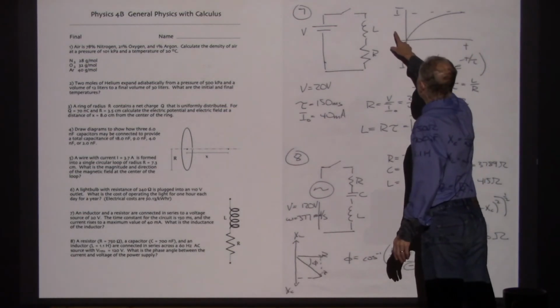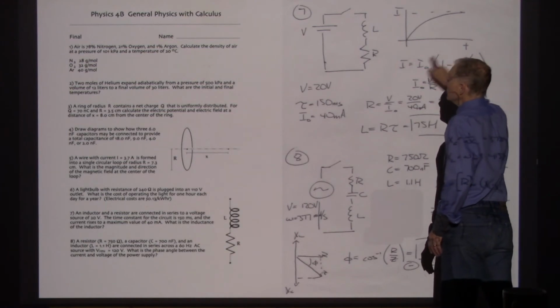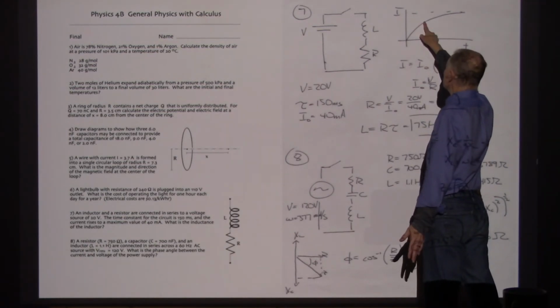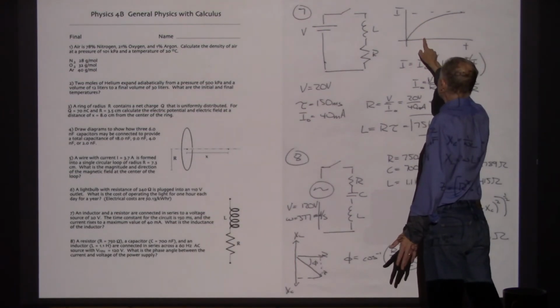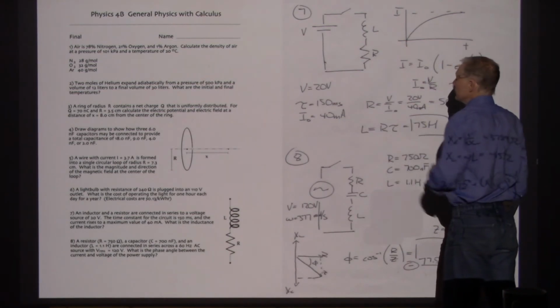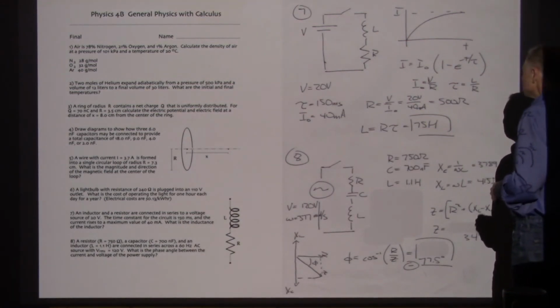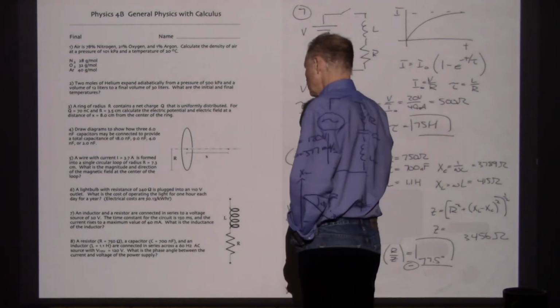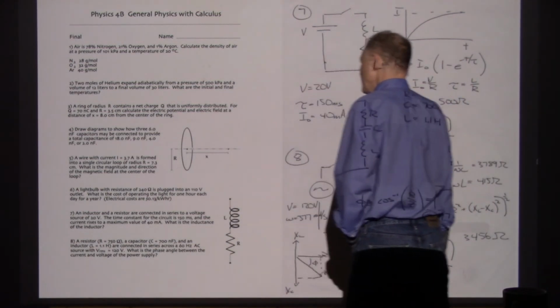So we've gotten out an oscilloscope and we've actually plotted the current as a function of time. Or similarly, we could measure what the voltage across the resistor is as a function of time. But here's our graph. So here is I as a function of time. And the time constant we've identified, there it is at 63%. So we brought that down and measured this on our graph, and it's at 150 milliseconds. And so what they wanted us to come up with is how much inductance do we have.